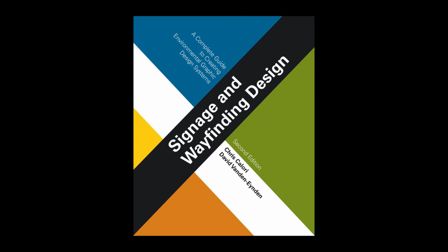But because fasteners often join dissimilar metals such as aluminum and stainless steel, they and the metals they join must be protected against corrosion that results from a weak galvanic or electrical reaction that occurs when dissimilar metals come in contact with one another.